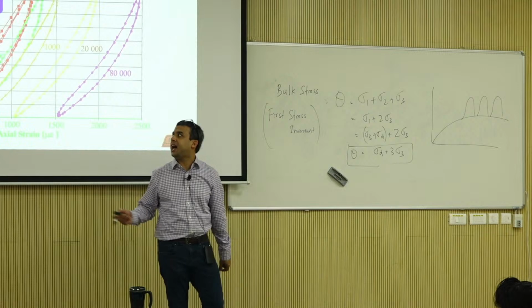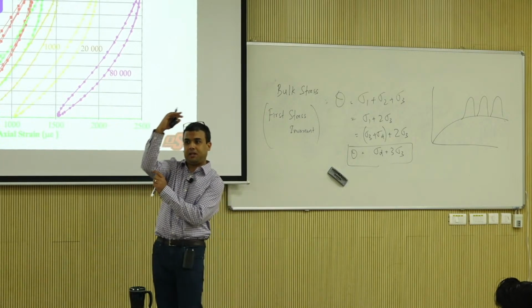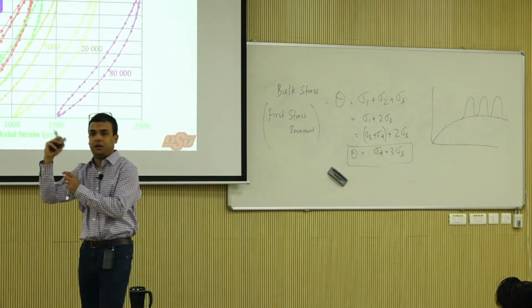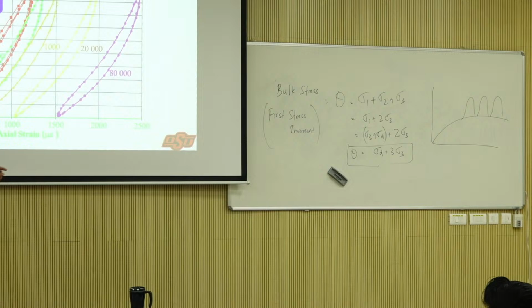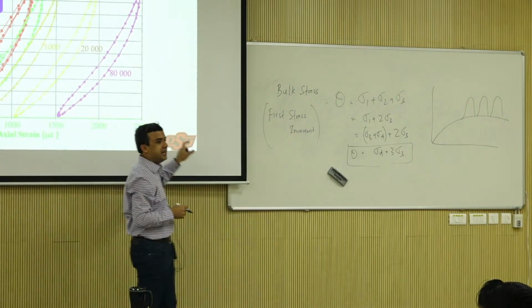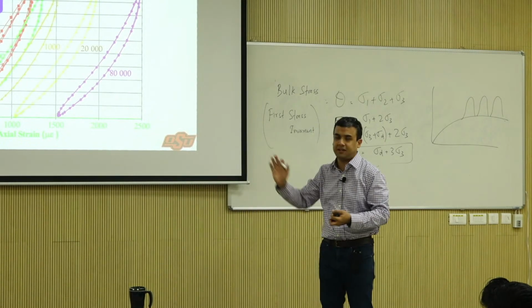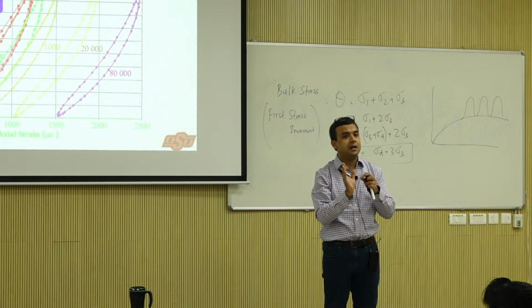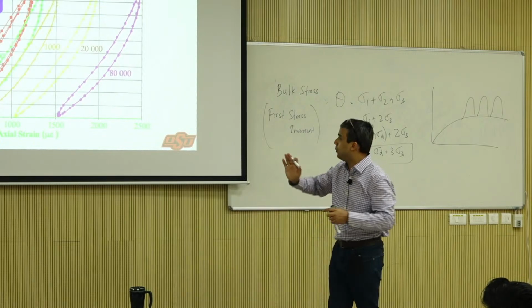Do you see how these shapes are concave up, like a saucer upward, not the traditional way of plotting? That is because for these materials, as the stress level increases, which is also as the strain level in this case increases, the modulus actually increases. Do you see what I'm talking about?